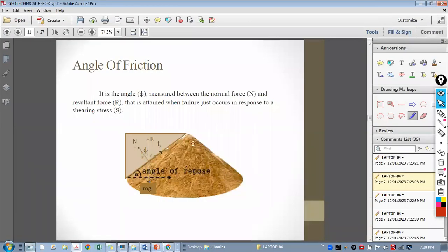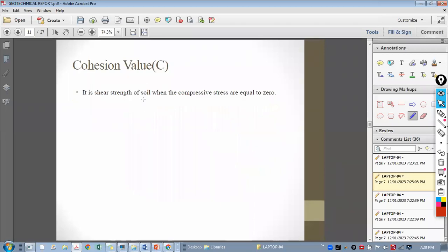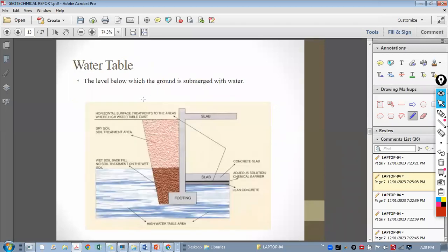And for that, we generally require this angle of friction data. All of you know that Ka = (1 - sin phi) / (1 + sin phi). So we generally use Ka gamma H for lateral pressure, and this K is nothing but this, right? And we require the sin phi values from this, the angle of friction values. Then cohesion, it is used for the SBC calculations.